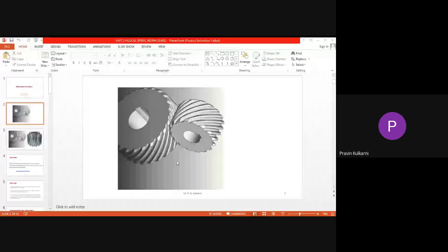Now, in case of helical gears, based on the diagram of that gear, we have to check whether the wheel is left or right. So remember that axis is to be vertical and the line inclination will show the hand of the helix.